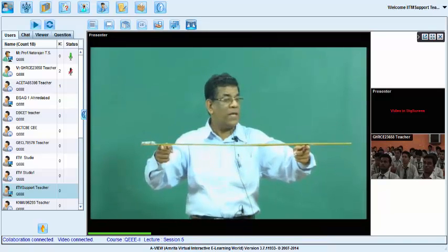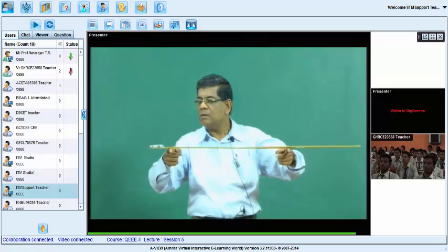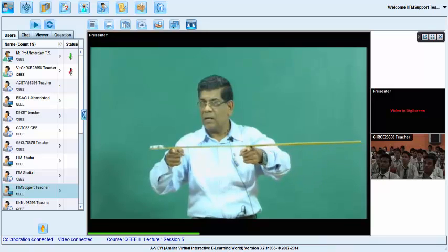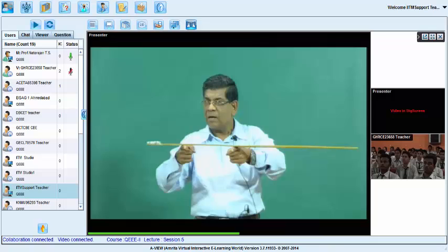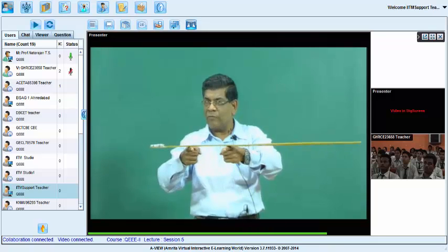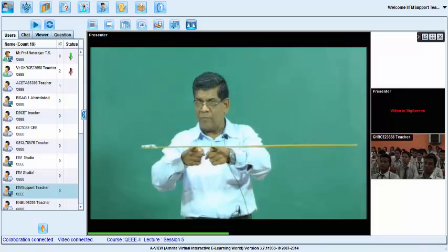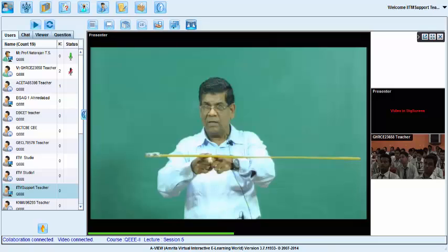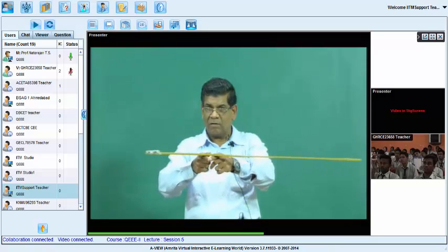But still this is slipping here. You can see that. See here, this finger is moving. Now this finger starts moving. Then you see, both of them alternately move. And finally, I end up at some point. What is this point? You all know it. This is actually the center of mass, right?